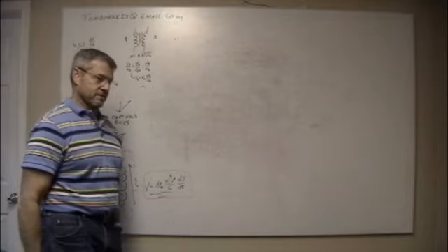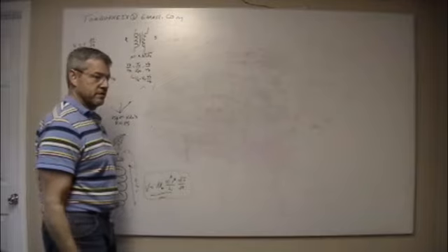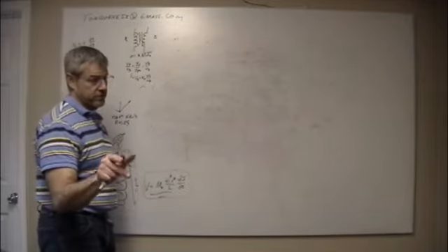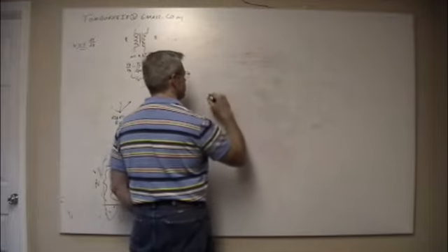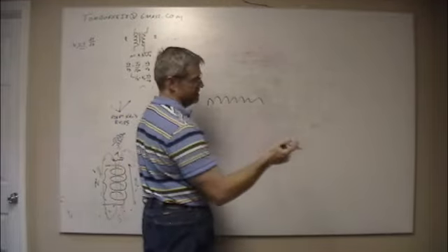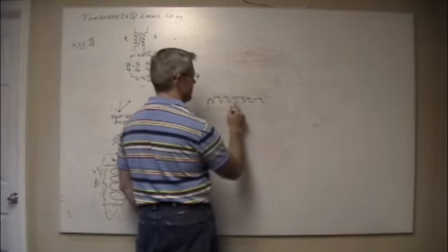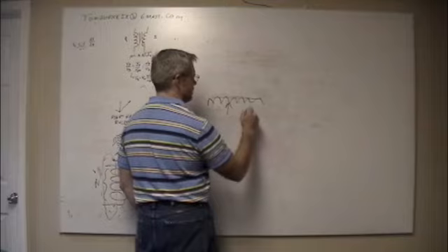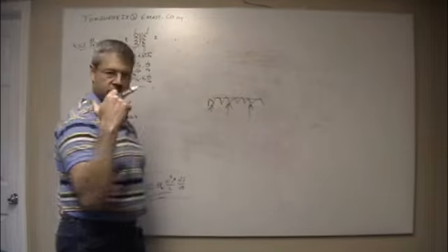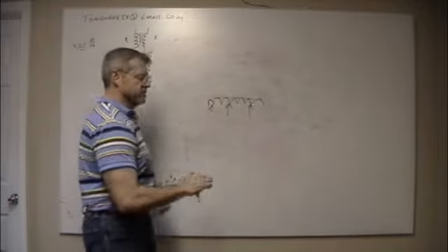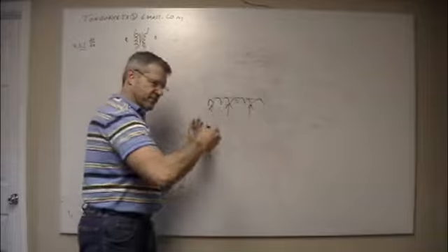A metal detector. The tuner on a radio, or an older radio, the way the tuner works on an older radio is there's two ways. You've got this big inductor, and you slide a pickup on it, and it changes the inductance going into the tuner coil. The other's with an air gap capacitor that they sweep through, and it changes the capacitance, same effect.